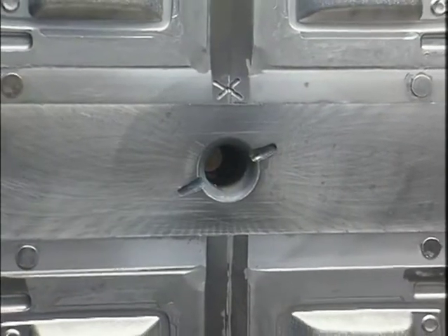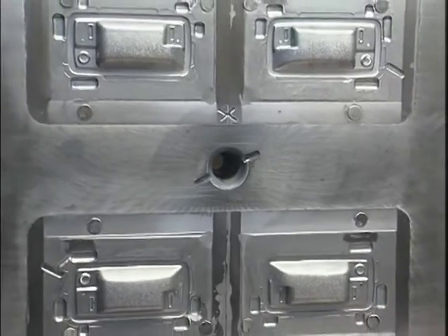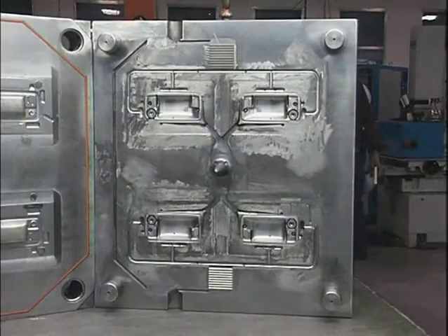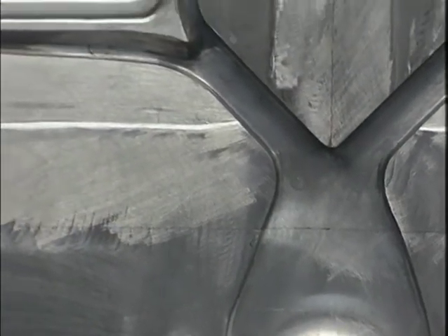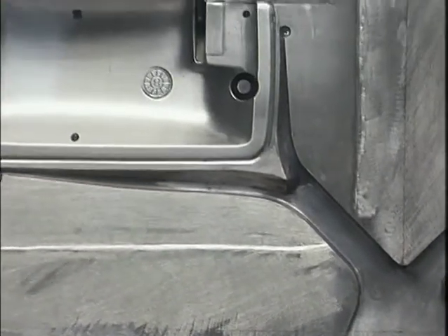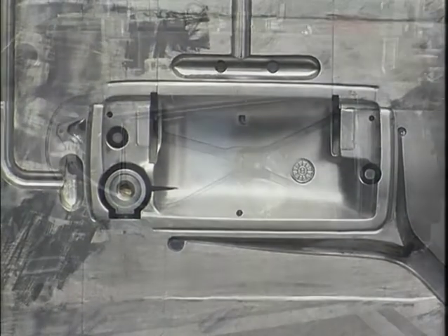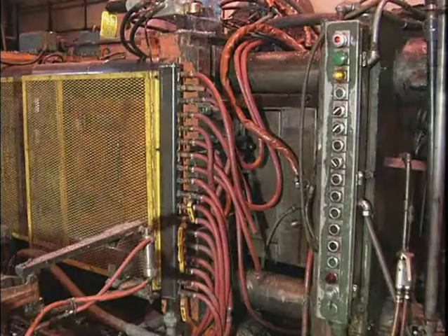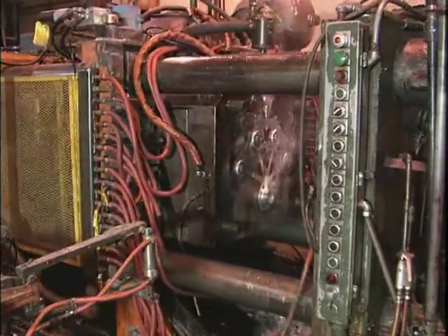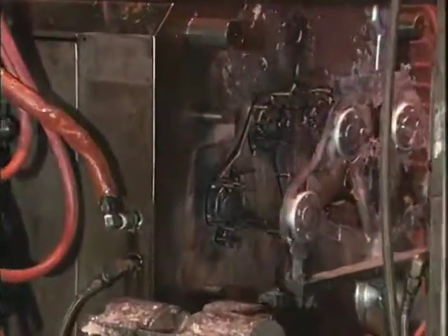The cover die half contains a port for entry of the molten metal from the metal injection system. The ejector die half usually contains the channels called runners through which the molten metal flows to reach the gate or gates at the die cavity. Dies are typically single cavity or multiple cavity dies. Multiple cavity dies are usually used for multiple identical parts.